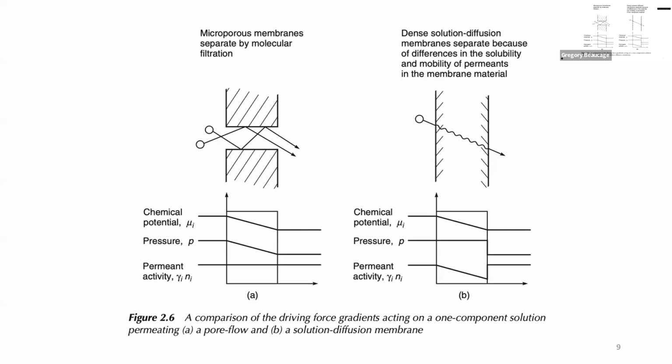Anyway, this just shows that the chemical potential, the pressure, would drive this one. So there's a pressure gradient, and here it's driven by concentration. The chemical potential is different on the two sides, pressure is the same, unless you have a pervaporation membrane. So if you have pervaporation, when you come through over here, it's a gas. Say you start with a gas and it becomes a liquid over here. So then you have water condensing on the surface, and that evaporates. So you have a combination of diffusion through this and then evaporation here.